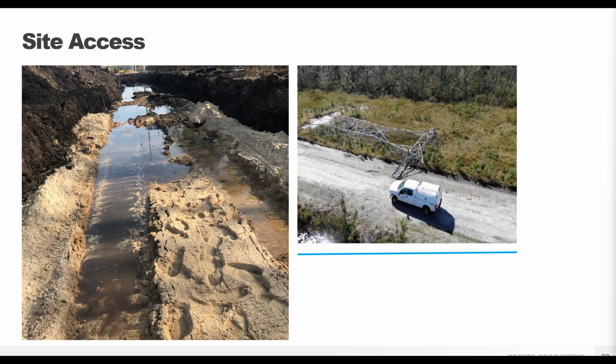This is a good GeoWeb load support project to demonstrate using the GeoWeb as its own site access during construction. This was a project for Duke Energy in Florida to install new transmission towers through the wetlands. Hurricane winds demolished over 100 towers, all of which had to be restored over this extremely soft subgrade, and the saturated sand couldn't support any type of vehicle loading.